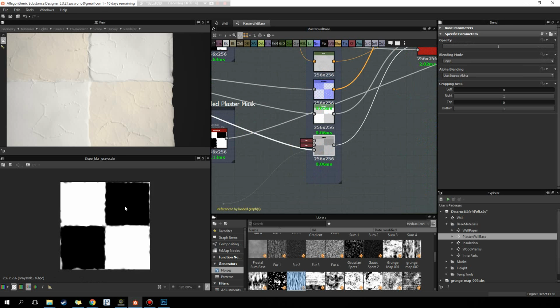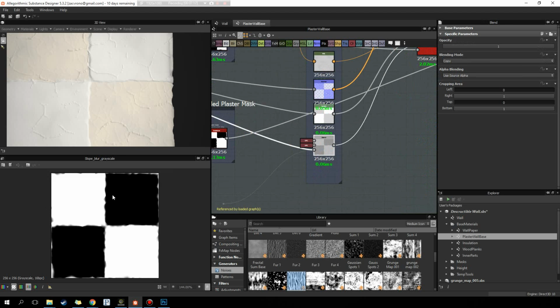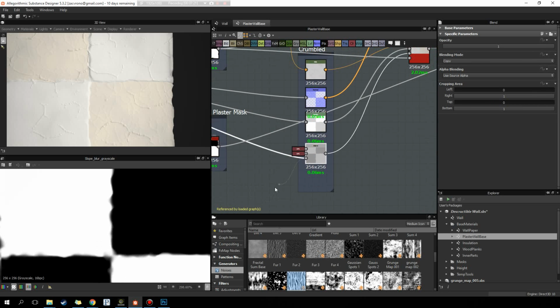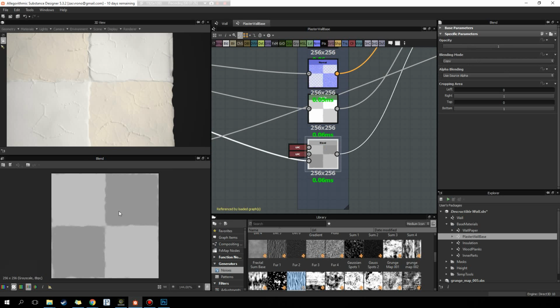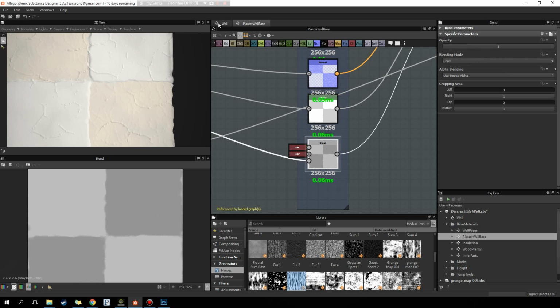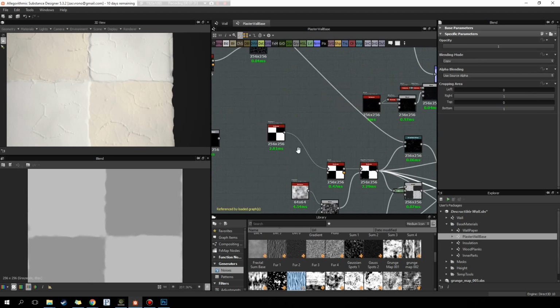So see now this, if I use this as a height map, that's too much. That's too black and white. It's going to be really stretched out far. So if I use that to blend between the two heights I want, it constrains it. The 150 being the lowest, 190 being the highest, I get this. And now this is an accurate representation of the height I want.